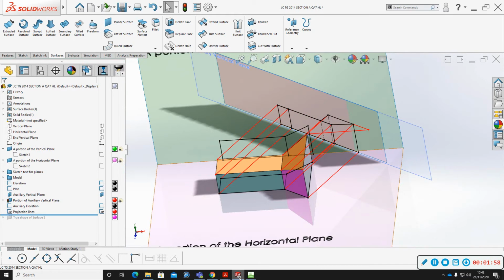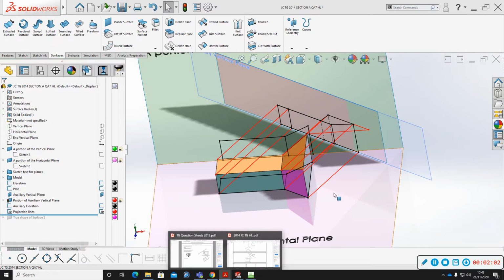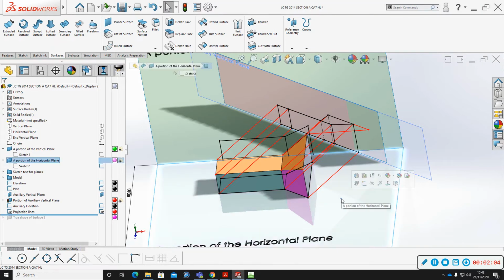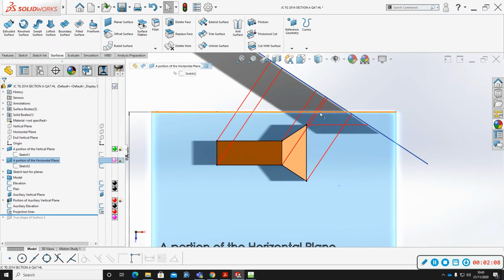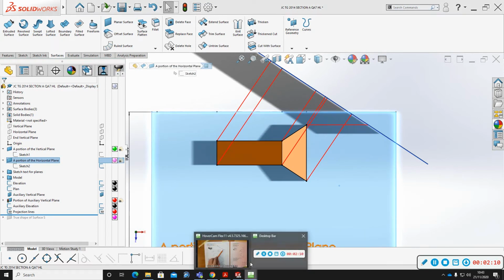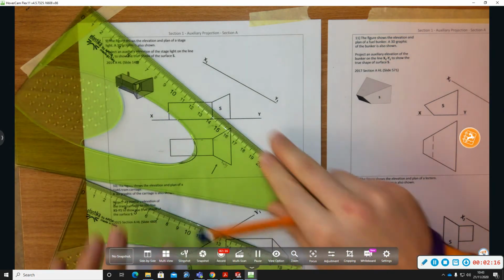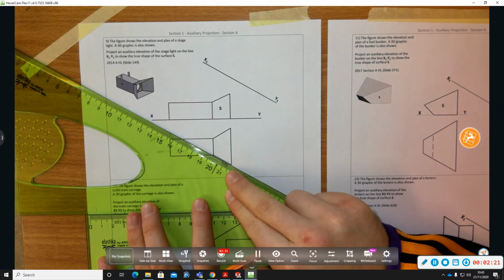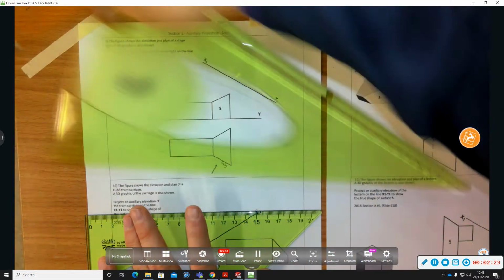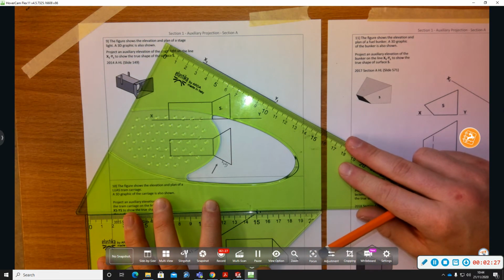So on our drawing sheet, these projection lines are drawn from our plan view. So we'll begin. I'm going to line up my set square with surface S, or the X1, Y1 line. So I have it lined up with the X1, Y1 line.